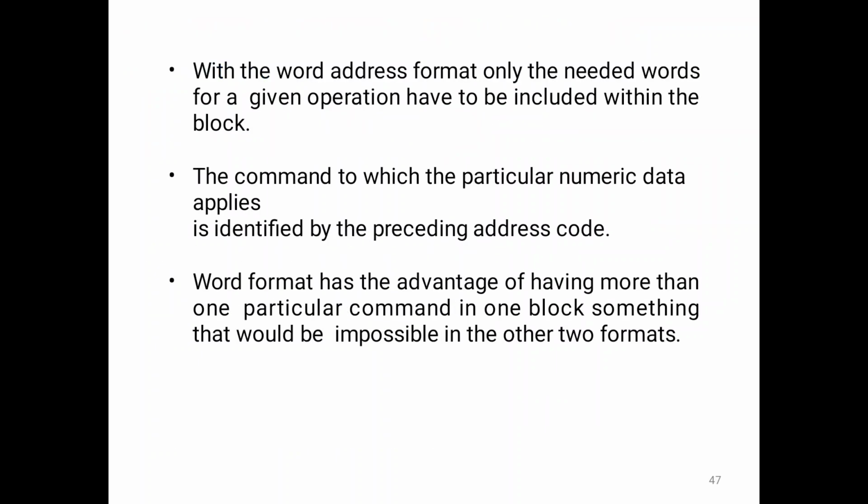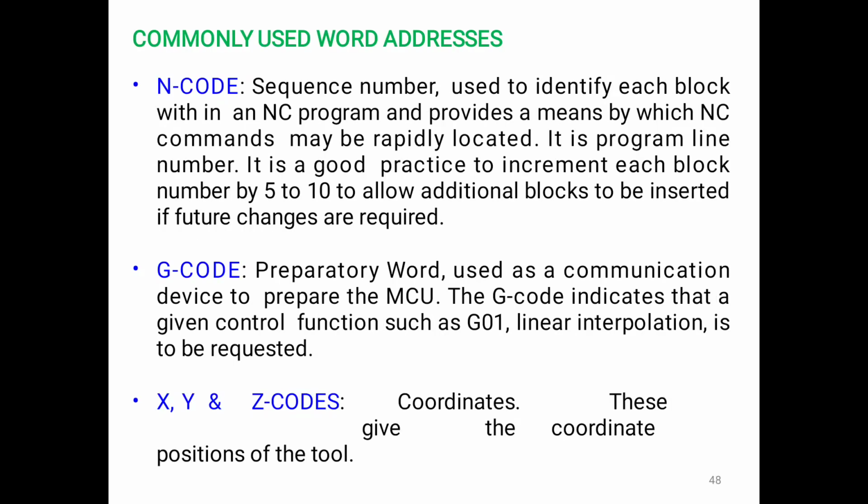With the word address format, only the needed words for a given operation have to be included within the block. The command to which the particular numerical data applies is identified by the preceding address code. Word address format has the advantage of having more than one particular command in one block, something that would be impossible in the other block formats.